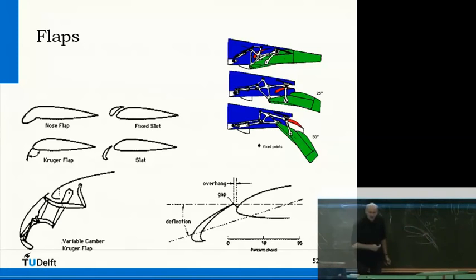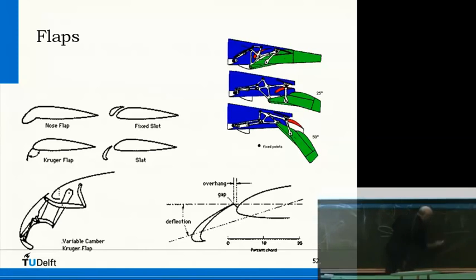It's the same as when you look at ailerons, for instance. If you have a wing like this, and you have ailerons here, then sometimes you see on a wing these small devices of this type or of this type. These are called vortex generators. Would the flow separate in front of this aileron, then it's not effective anymore.